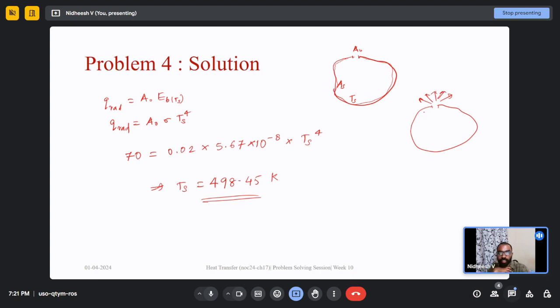But what about the radiations from these surfaces? It is going in all directions, and these radiations are again striking here, and here. So when we consider this area for radiative emission, whatever radiation is emitted gets reflected here, again reflected here, and again here. Finally, whatever comes out is through this opening, and that is the final radiative power of this black body.